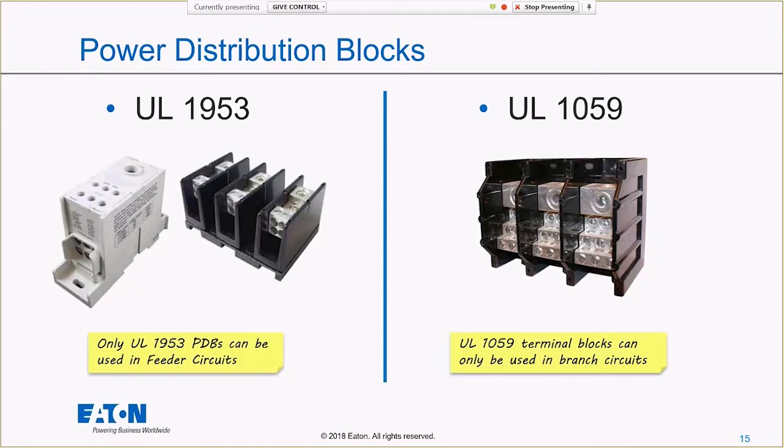Really, really important. You don't want to be using the UL 1059 recognized block in your feeder circuits. It is absolutely a misapplication, and I think this is one of the most common misapplications I see. A lot of this is just that if you don't know there's a difference between a UL 1953 power distribution block and a UL 1059 recognized one, you're probably going to